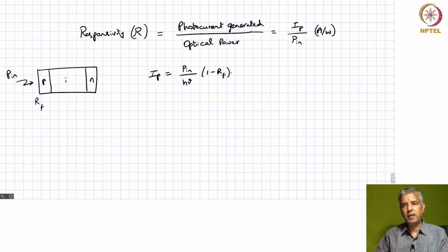Now, not every photon that goes in gets converted to an electron-hole pair. There is a certain photoelectron conversion efficiency, let's call that zeta. Typically for direct bandgap semiconductors, zeta is on the order of 0.9. For an indirect bandgap semiconductor, it could be down to about 0.7, but it's around those values. So that is actually the conversion efficiency.